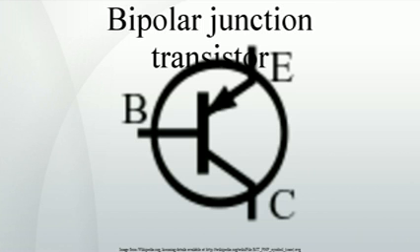In contrast, unipolar transistors such as the field effect transistors have only one kind of charge carrier. Charge flow in a BJT is due to diffusion of charge carriers across a junction between two regions of different charge concentrations. The regions of a BJT are called emitter, collector, and base. A discrete transistor has three leads for connection to these regions.